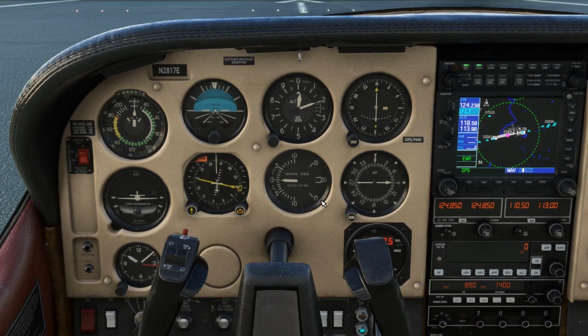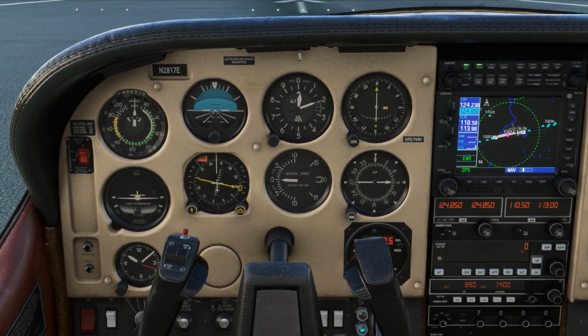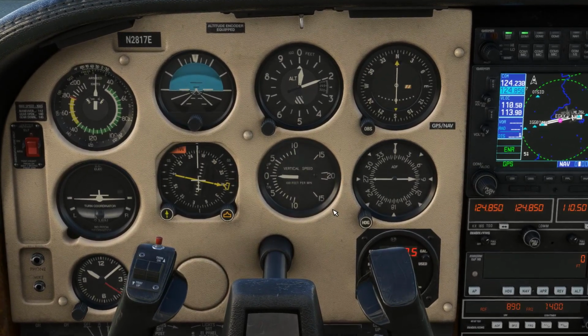And the other thing I look for is the vertical speed indicator. Now, many of you will know this, but I'll go over this with you again. They're all pretty much similar vertical speed indicators. They may look slightly different in different aircraft, but they'll have a similar format. You'll have an arrow here, an indicator to show what vertical speed you're doing. Obviously we're on the ground, we're not climbing or descending. So vertical speed is basically you'll either be climbing or descending. We're on the ground, so it's pointing towards the zero.